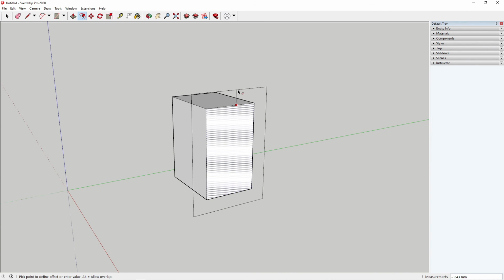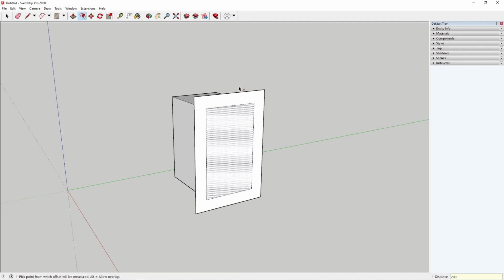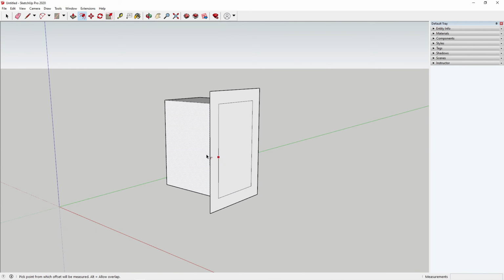So if I want to drag out 225, you can follow this and just want it to have a rough length of 218 mm, just click, or undo, and I want it to have a precise dimension of 200. You type it inside the distance and then you press enter. Can you see how very useful this is? Then after that, you can choose to just extrude.